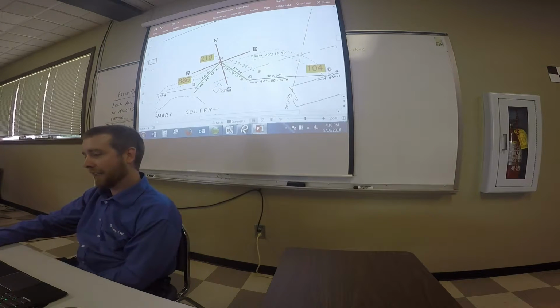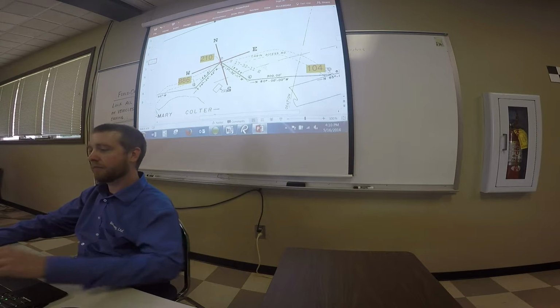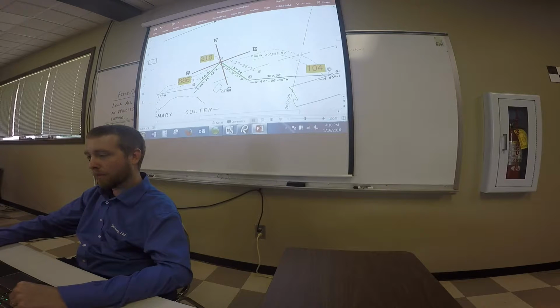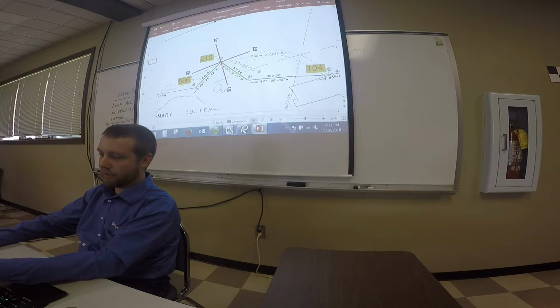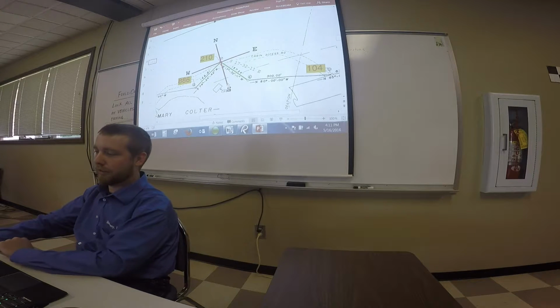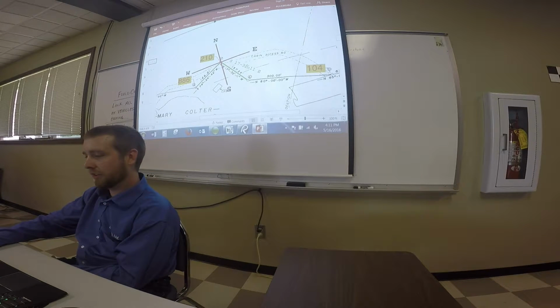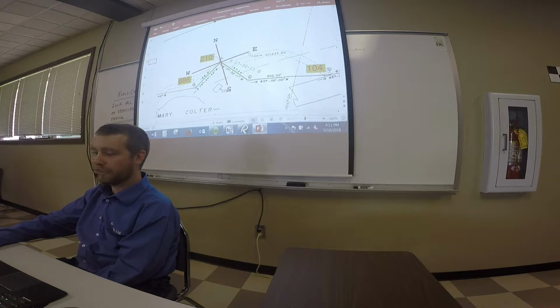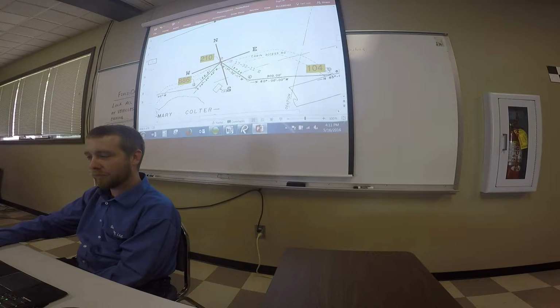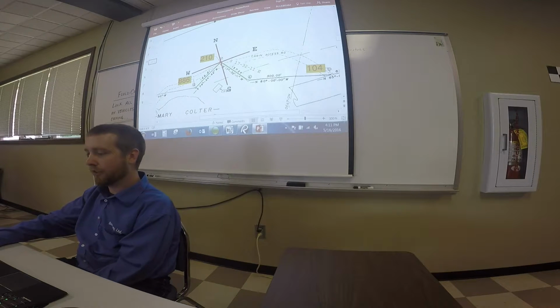So this is what I was saying, the north 17 west is also south 17 east. Now we know the way bearings work: with south 74 west, you start at the south line, then you go 74 degrees towards the west line. On the southeast, you start at the south line and then go 17 degrees towards the east line to get south 17 east. And the angle we're looking for is going to be the angle in between these two green lines.